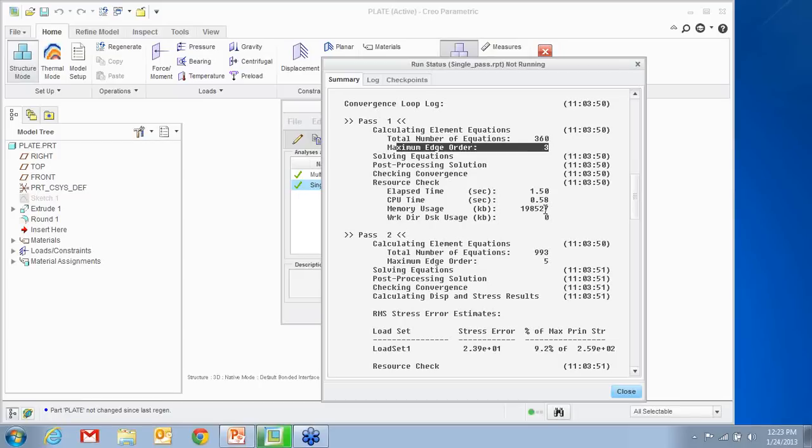So you go to a second order. Now, if it is a complex geometry, it might jump up the element's edge order to, say, 3. In that way, it can go up to a polynomial order of 9. The advantage of that is that as your complexity in terms of geometry increases, we get an exact match to the geometric boundary with our mesh elements, because the element edge orders can match the geometric boundary shape.